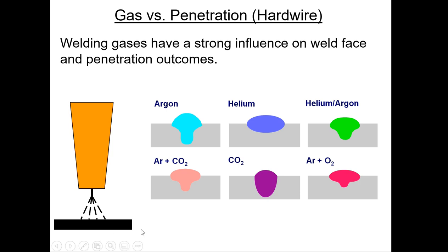I have tuned up a lot of these for 90-10. I'm sure that most companies are about 90-10. 85-15 is still very common though. Carbon dioxide, there's a lot of plants that decide they're going to use straight carbon dioxide for the welding process. It's a little surprising, but given certain welding equipment, you can weld with straight CO2 very well, and straight CO2 is 1/10 of the cost of regular argon.